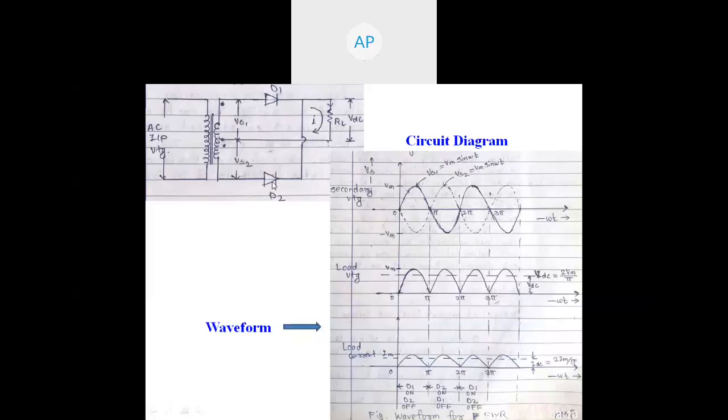If you take a mirror image of this diagram, or vertically rotate the circuit, you will have the same as a half wave circuit. Remember that at a time only one diode is conducting, so only one forward resistance comes into the picture.